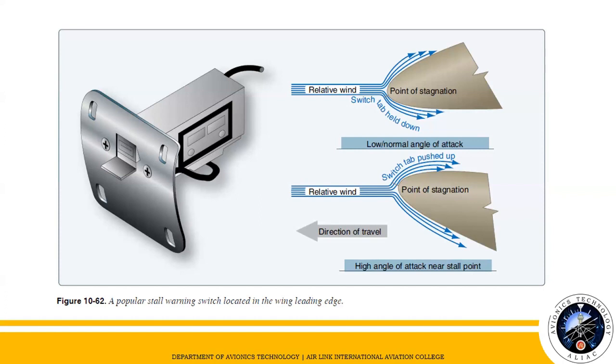So, a true AOA indicating system detects the local AOA of the aircraft and displays the information on the cockpit indicator. It also may be designed to furnish reference information to other systems on high-performance aircraft. The sensing mechanism and transmitter are usually located on the forward side of the fuselage. It typically contains a heating element.